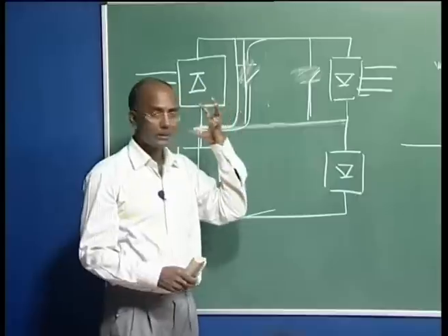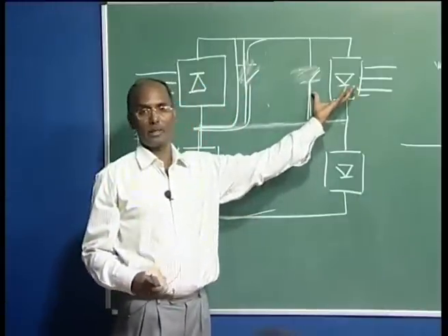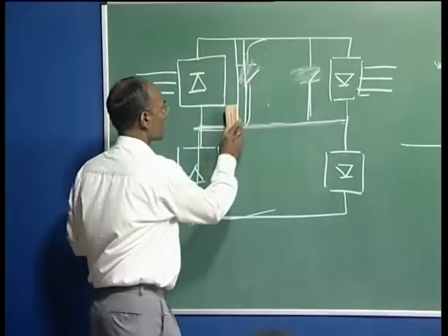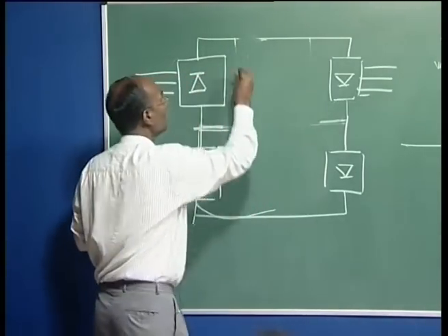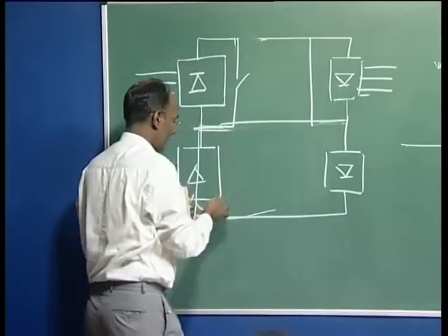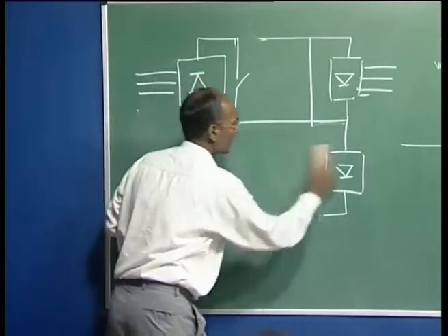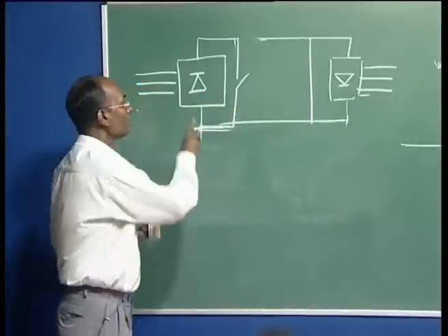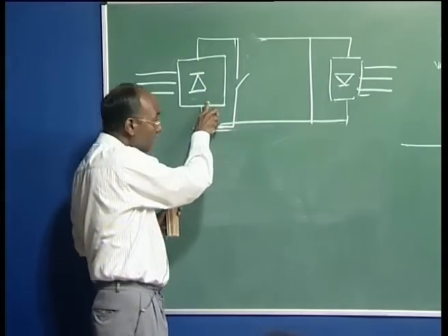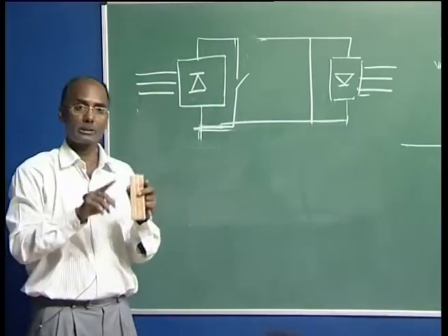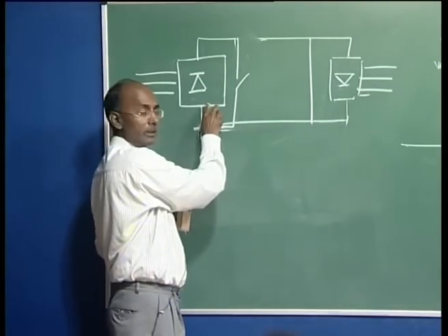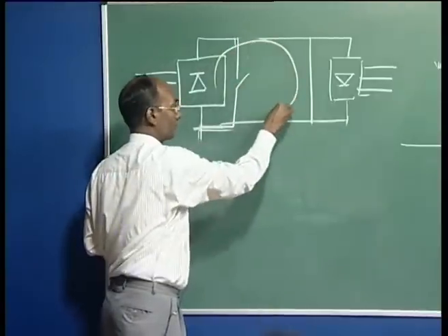So, the one which you deblock, you operate as a rectifier. If you are taking this as the first one, let us see. What we did, we opened this. This was already closed, and we are talking here only about monopolar operation for simplicity. Now you are just deblocking this, meaning you start giving the pulses. Now it will be conducting. The pattern follows the sequence 6, 1, 1, 2, and this symmetry will always be there. So, we are generating some small voltage here, and the current will start flowing.